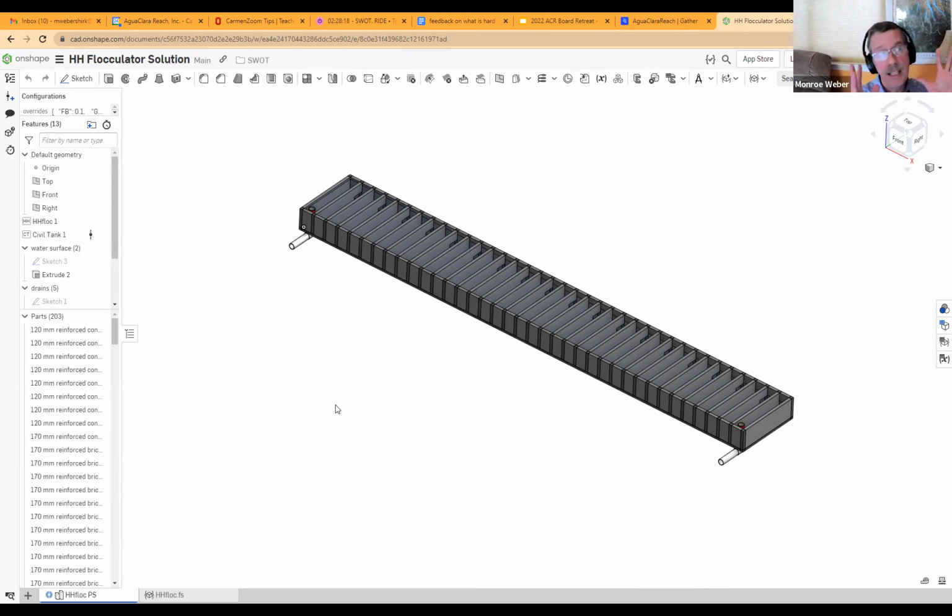So that makes it a little bit easier to do this design because you don't have to figure out how wide individual channels need to be. That's because the human constraint doesn't show up here. These are big flocculators and there's no difficulty getting a human in between these baffles. So that ends up not being a significant constraint for this design, whereas for the other designs, that was a critical part of the constraint and that made the design more complicated.